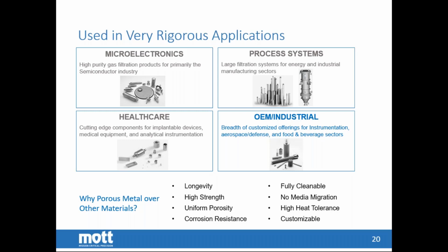Can you just, Alan, Chris, give us a brief overview of why people tend to choose porous metal over other materials like plastics and even sometimes ceramics or various cloth materials when they go to make a decision? Well, in the case of plastics, there's usually a temperature limit that they can go to, maybe 400 degrees Fahrenheit. And above that, you really need to get into metals if you're concerned about heat resistance. The other thing, too, is metal compared to plastic is stronger media.